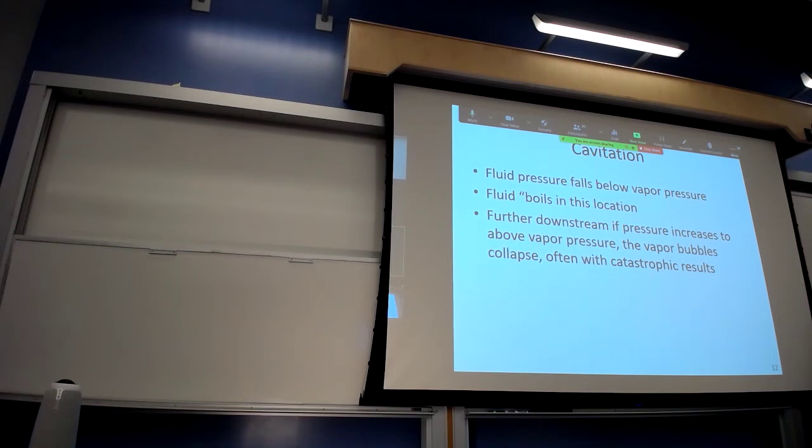So in some of the ships that we were mass producing during World War II, after 6 months out at sea, ships' propellers, and these were enormous, almost the size of this room, they would come back almost paper thin because of the cavitation process. And obviously, it's happening around the edges or elsewhere. As that ship's propeller gets weaker or smaller, you can't thrust the ship as much anymore.